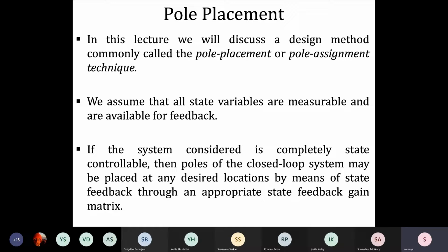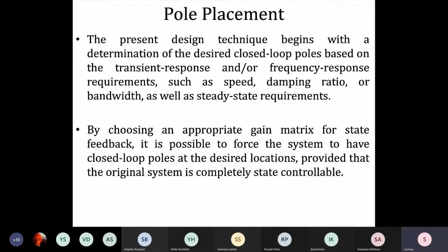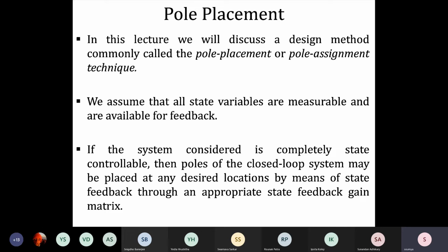Similarly, if we look at the S domain based transfer function for the system, we look at the position of the poles, and if they are all in the left half plane, then again it's a stable system. Otherwise, on the imaginary axis, it's marginally stable, and if any pole is in the right half plane, it's an unstable system, right? So we'll make a few assumptions here.